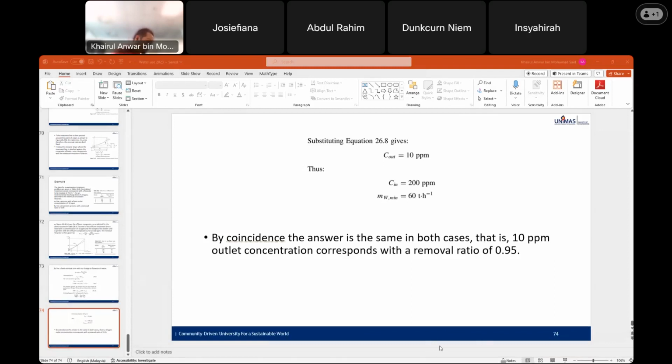Yeah, that's all for targeting the water for reuse. So to recap, you have learned how to target maximum water use for a single contaminant. This is based on the limiting composite. Any question, just ask. And we have a four-step procedure to design the water network, either for reuse, or when we have a new water source, or to know the impact of water loss.